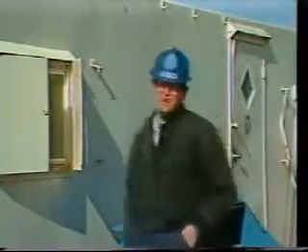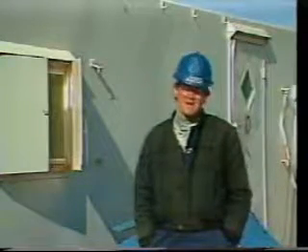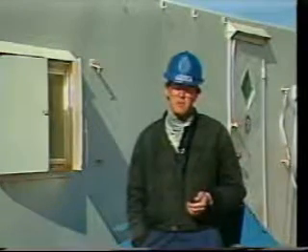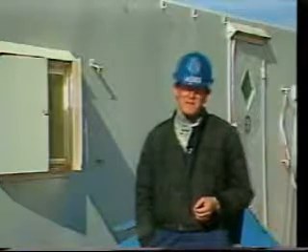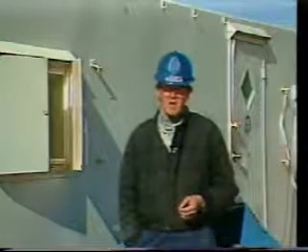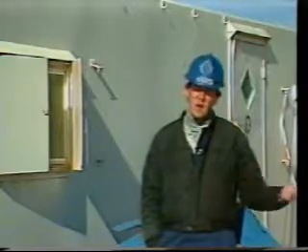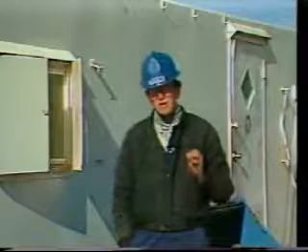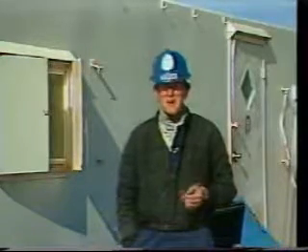Tripping can take many hours in a deep hole, and time is money, particularly on a drilling rig. We don't want to make any unnecessary trips, so we try to drill as far as we can with a bit before pulling it, or as deep as we safely can before setting casing. Of course, if we push our luck too far, an overworked bit could drop a cone, or trying to drill a long open hole section just a few feet further before setting casing could result in stuck pipe.